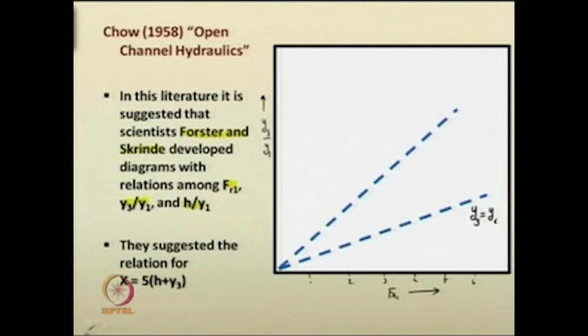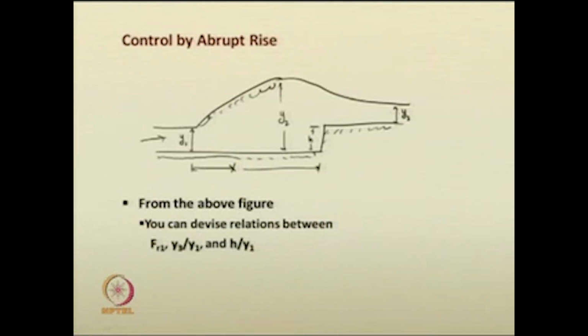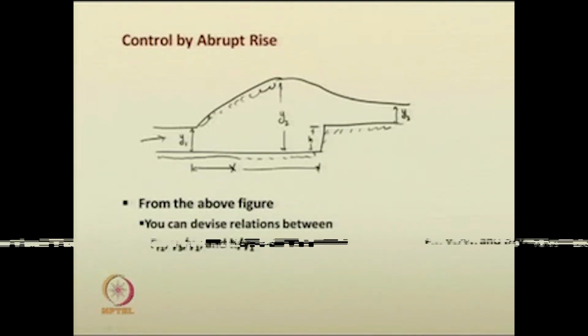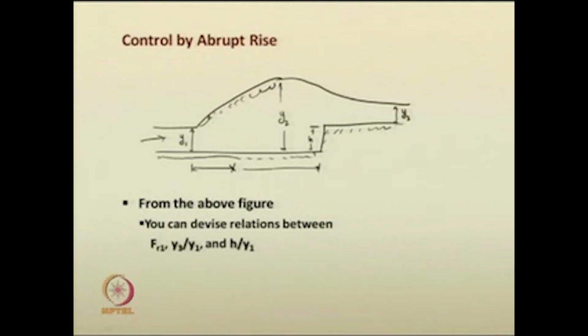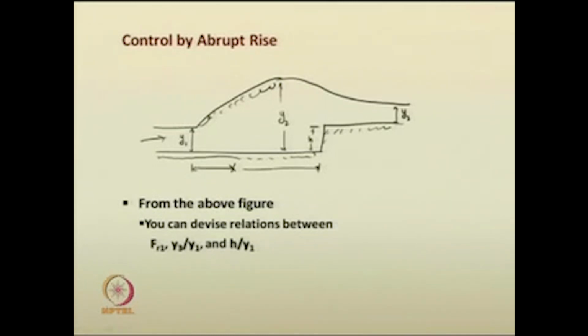If you recall the earlier figure, this is y3. So, if the flow over the sill is critical, that is after the channel bed has been elevated, whatever the flow depth, that could be the minimum possible, meaning you cannot go beyond that in such a situation, for whatever elevation. For such a control, it definitely cannot go into the supercritical condition.